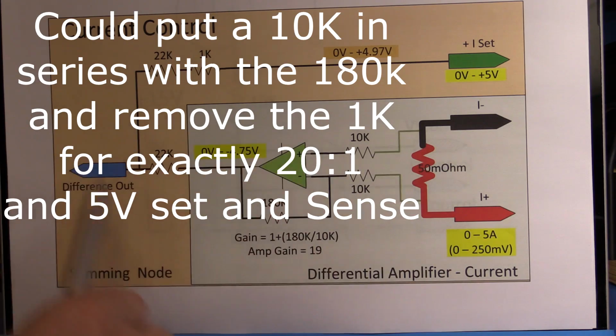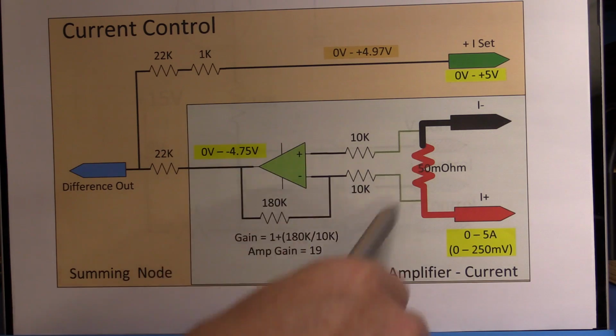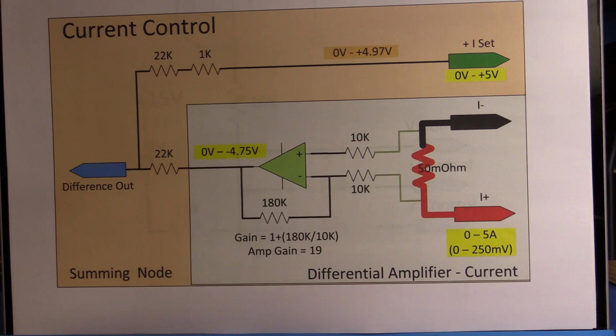What is more important with these components is that the system is thermally stable and stable over time as well. You don't want them to be drifting in a way that would increase your errors. So with a differential amplifier, normally because both sides have the same values in it, they usually compensate for each other. So they'll move around, but they won't really change things too much, because the feedback and the input resistors and everything else are all of the same kind.